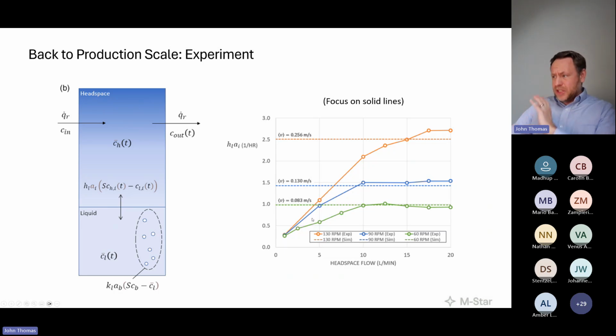And again, we talk about this in depth in the paper that was published, but I'll summarize this point one more time: we cannot claim to be reliably measuring a convective free surface transport coefficient and a convective free surface transfer rate until we can be ensured that our headspace is in fact well stirred, homogeneous, and constant. If we are not in that regime, we have this very complex convolution of an impeller speed dependent HLA, a mixture dependent concentration, a turnover time dependent concentration, which can mess up our HLA, and our results are not reliable.